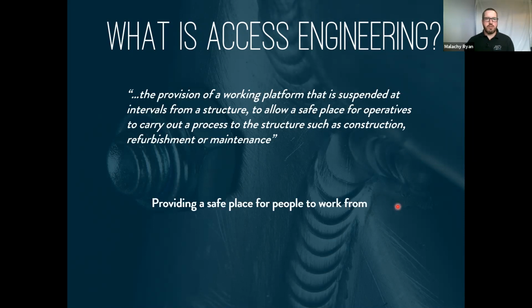So if you're looking at a project where you're doing repairs to the underdeck of a bridge or any type of bridge structure, then the actual challenge there is getting the operatives to the workplace in a safe manner. Yes, the main priority for the work is the concrete or steel repairs, but that's a smaller proportion of the project in terms of design and workload.